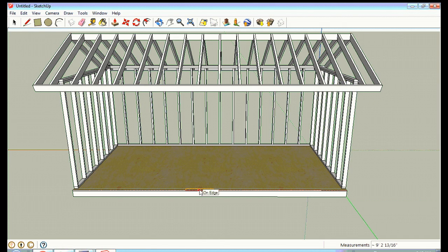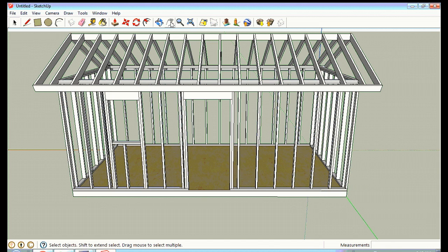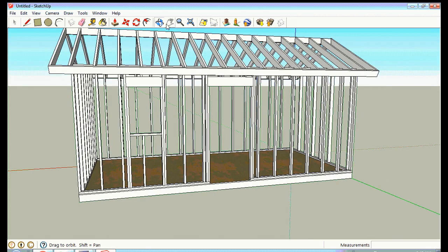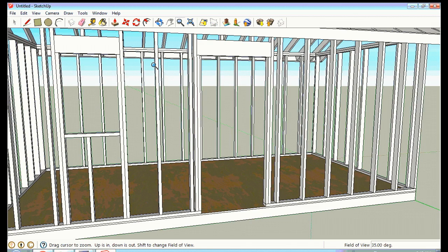Again, my wall disappears, so I get the orange box, and I'm just going to go along this edge where I think I want that window. Okay, I'm going to put it right there. Now it puts in my window, as you can see, exactly the same height as the door, so it looks right. And again, these are called king studs. You've got king studs on the inside of the window, and you've got a header, and then you've got a single sill plate of a 2x4.